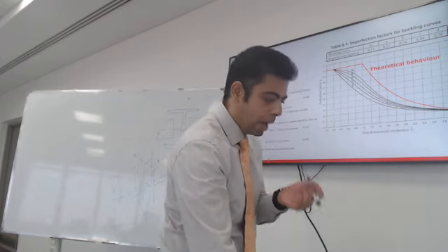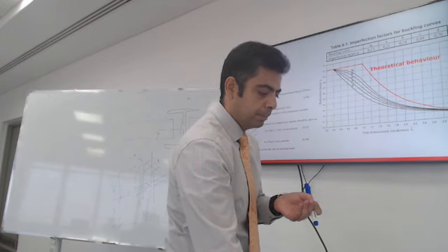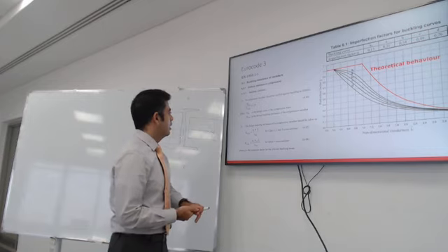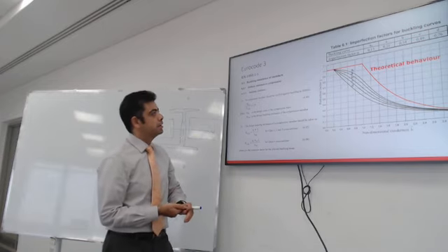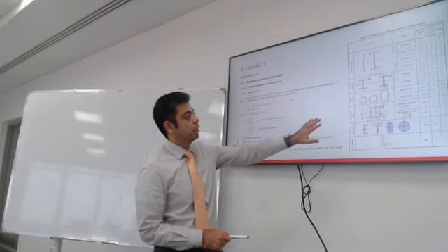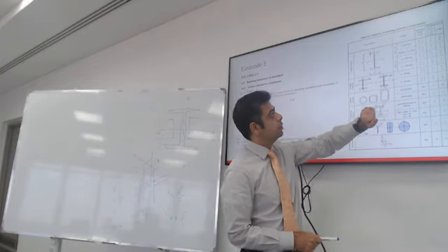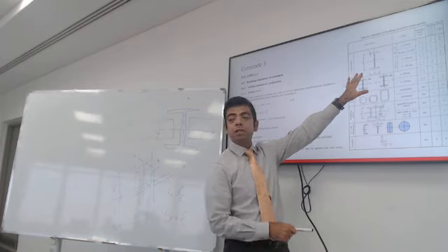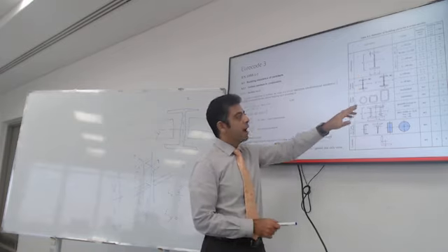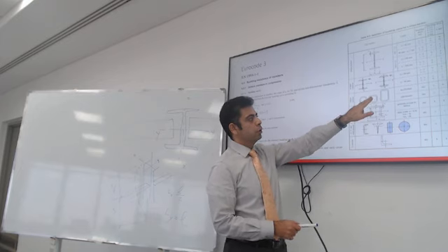All right, so how do we get these numbers? What do we need to get the imperfection curve? How do we choose the imperfection curve? Well, it depends on what shape you design your column to be. And let me say this, I like hollow sections and closed sections for columns.